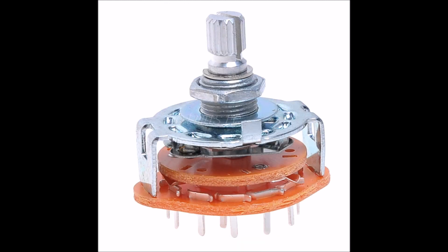Or, dispensing with the control switch, 3P4T rotary switches, or 4P4T slide switches can be used. When substituting 4P3T for the 4PDT on-on-on switches, switch position layout will be flexible, and can be customized to make it possible for transitions between certain favorite combinations to require moving only one notch of one switch. This makes an excellent all-around switch system, whether for a studio guitar, or a live guitar. Considering the alternatives, this system can be reasonably cheap, or very expensive to build.